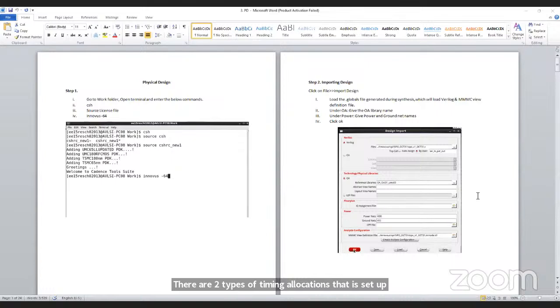So the timing concept is called static timing analysis. Whether you do setup timing analysis or hold timing analysis, whatever the timing analysis might be, it is called static timing analysis. Whereas analog circuit design engineers do manual timing analysis, that is dynamic timing analysis. They do this timing analysis based on the circuit, and here we have the circuit based on our synthesis netlist. Clear everyone so far?